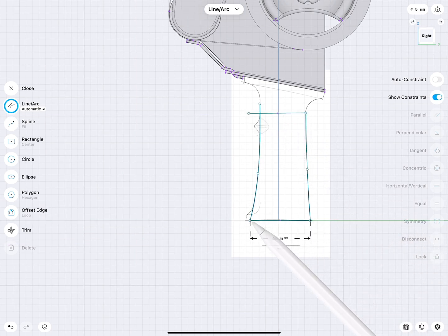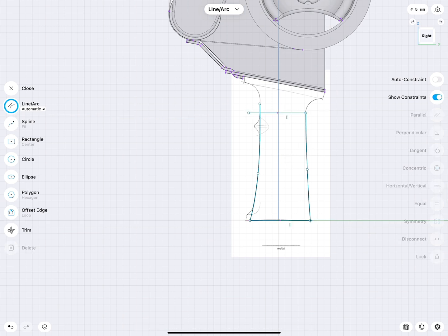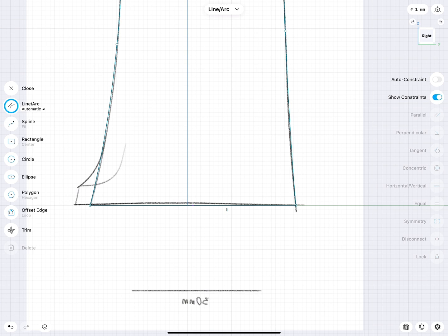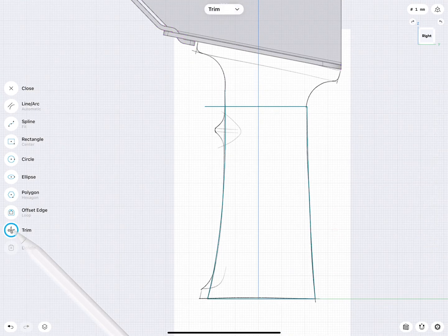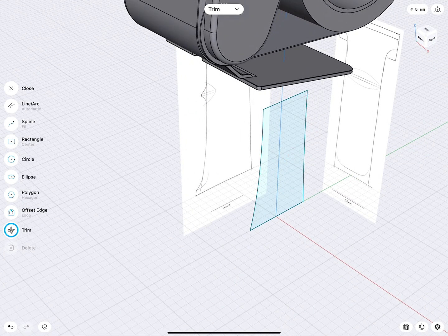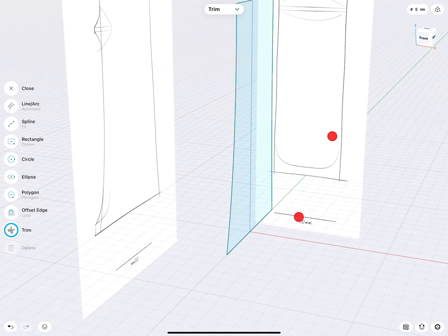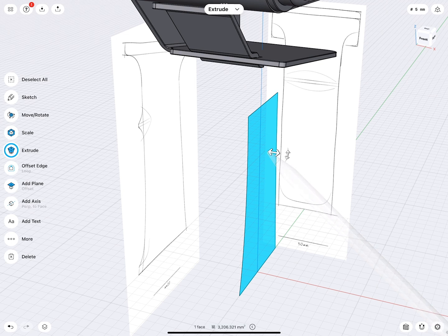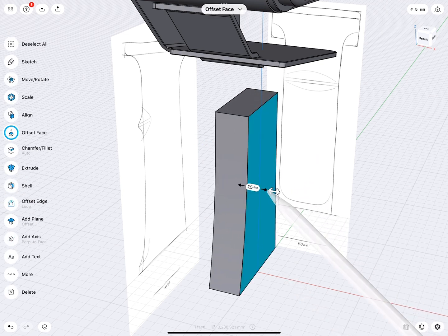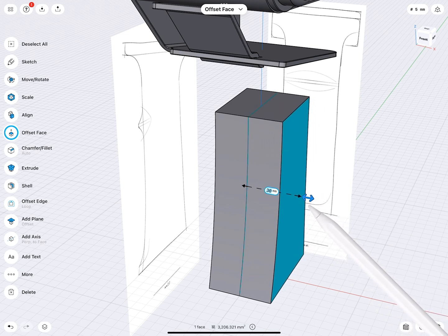I will draw 2 horizontal lines. And then I make them vertical and horizontally constrained. That's very good. Along the grid, trim, cut these 2 pieces off. Very good. This might be all I really need. The whole handle is 30 millimeter wide. So it means from this view now, I can push and pull and extrude this by 15 and then another 15 to this 30.